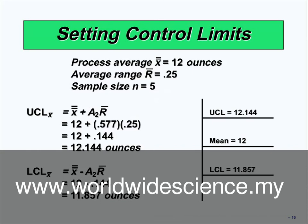In this new example n equals 5, sample size is 5, so the A2 from this table is 0.577. Yes, very good. So UCL, or upper control limit, or maximum number, can be calculated by X bar, which is 12, plus A2, which is 0.577, times R bar, which has been given to you as 0.25.